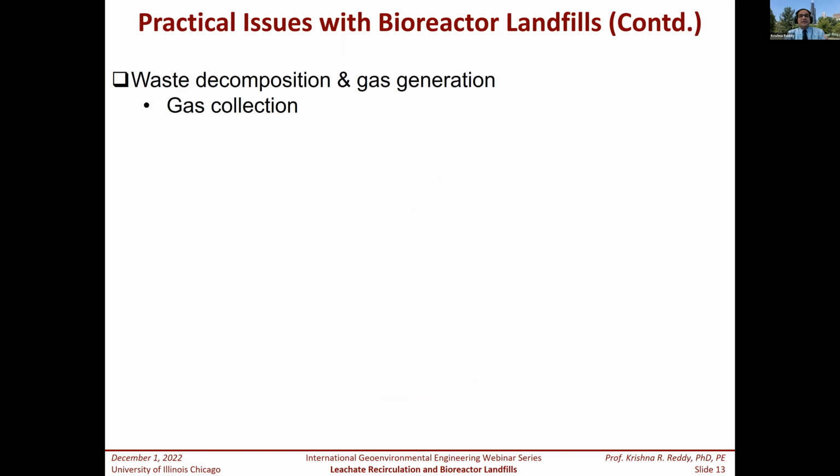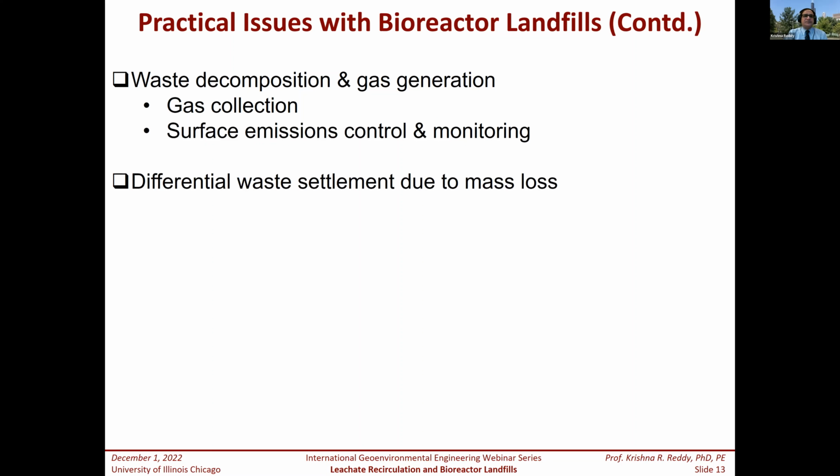Now, another important thing is the waste decomposes really fast. So the gas generation occurs really earlier than in conventional landfills, and you're getting a substantial amount of gas. So you have to put in these gas collection systems much sooner than under conventional landfill conditions. And also, you have to do extra surface emission control and monitoring, because you don't want any gases that are generated to not be captured. And you could have issues with compliance with the regulations.